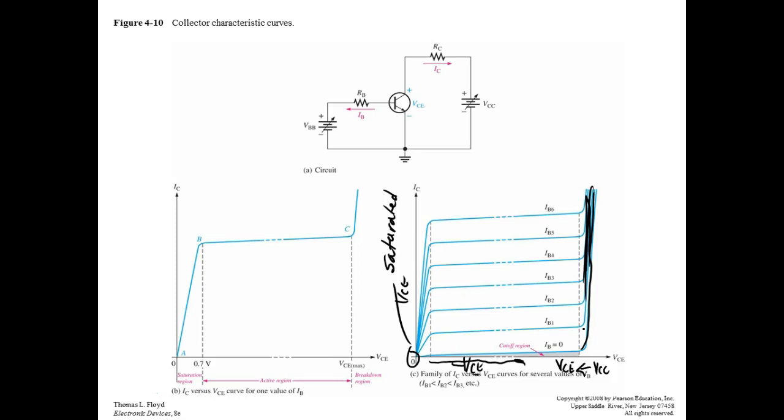Now, the problem is when a transistor goes bad, it can go bad 3 different ways. We can open it. We can short it. A transistor will short. All solid state devices will short. Or it'll be what we call leaky, which means it doesn't work. It acts like a resistor. It doesn't act like a semiconductor anymore. So this is one of the major things we're going to look at.